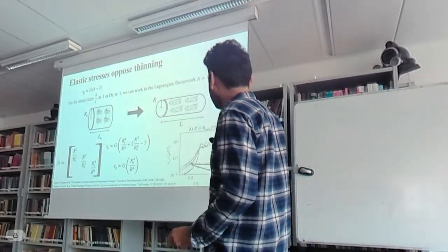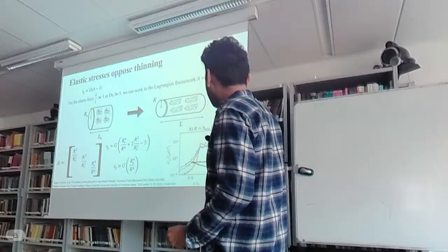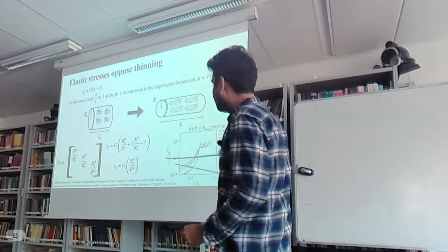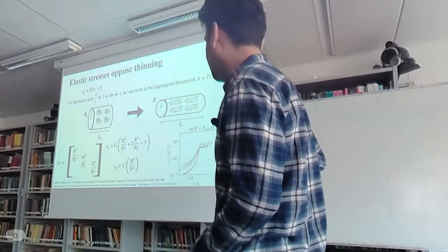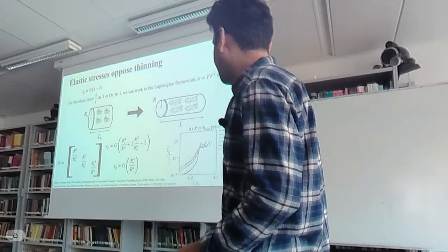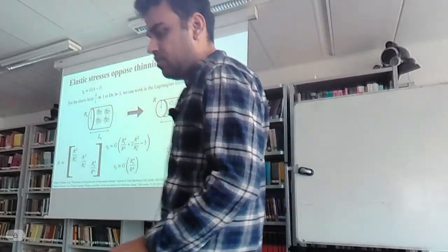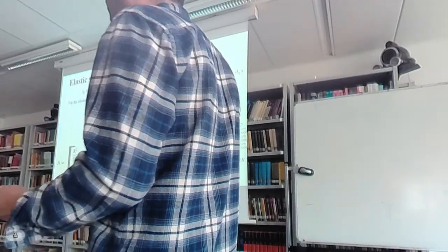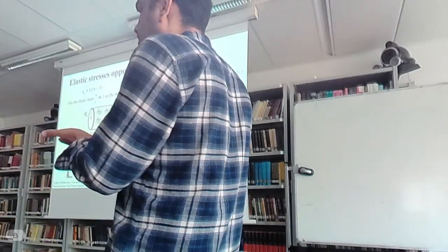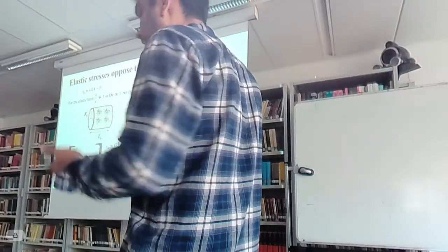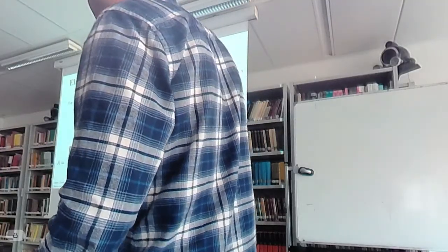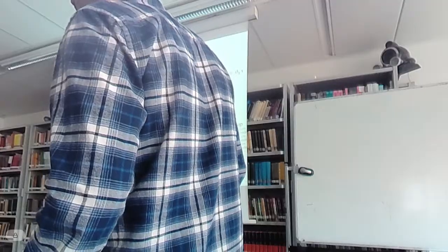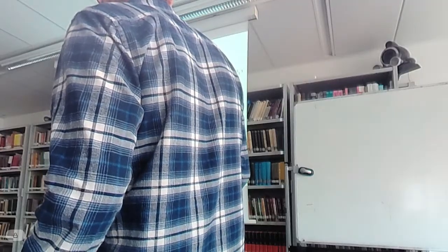So here the simulations are dotted lines, and the solid lines are from the model that I just presented, and you get a fitted value of Re. And then at large Deborah number, this tells you that you will go to a constant height, right? Which was the prediction from the fully elastic theory.